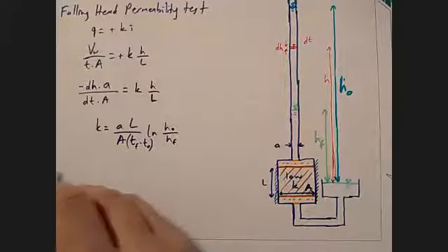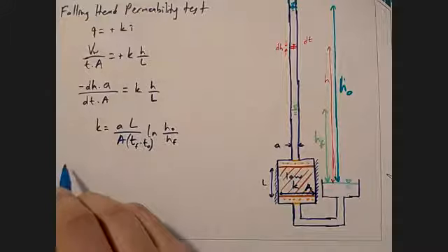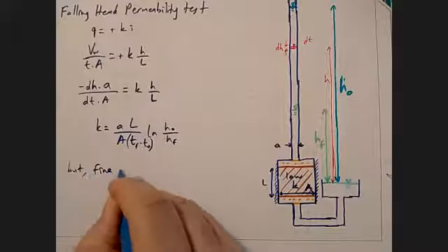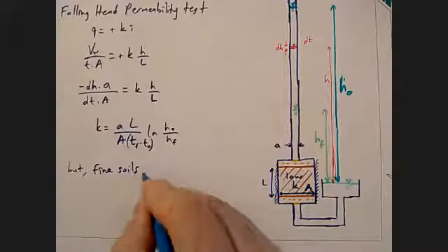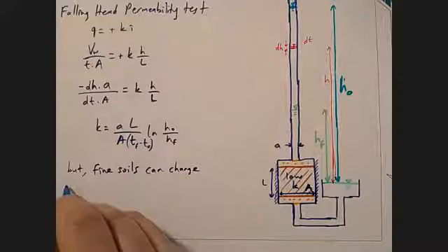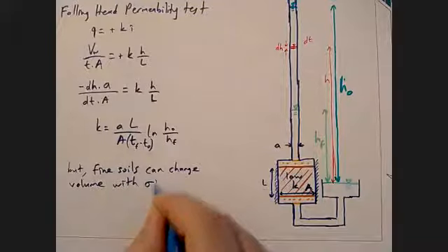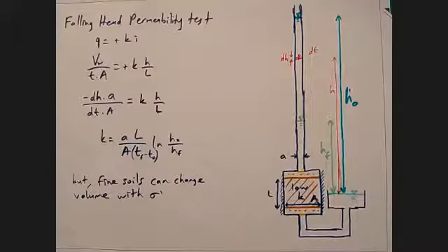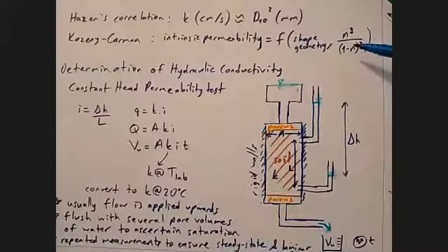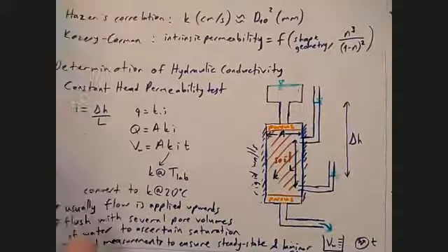But the problem is that fine soils can change volume with stress. Why does that matter? Well, if volume changes, porosity changes. If porosity changes, that affects hydraulic conductivity.